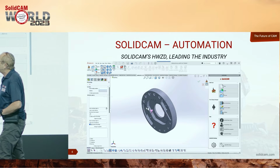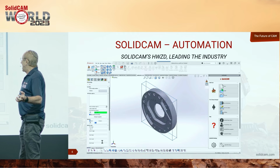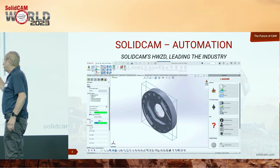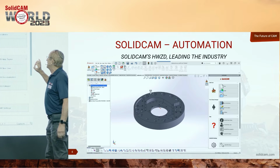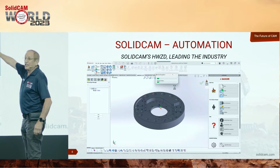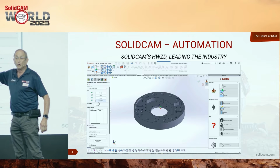So now we're going to create a CAM project, and we're going to create a home position. I like to always add also the X or Y position, in this particular case the Y position. And I have it set up so that it's automatically recognizing the target and the feature. As it's recognizing the target, it's already recognizing the holes as well.